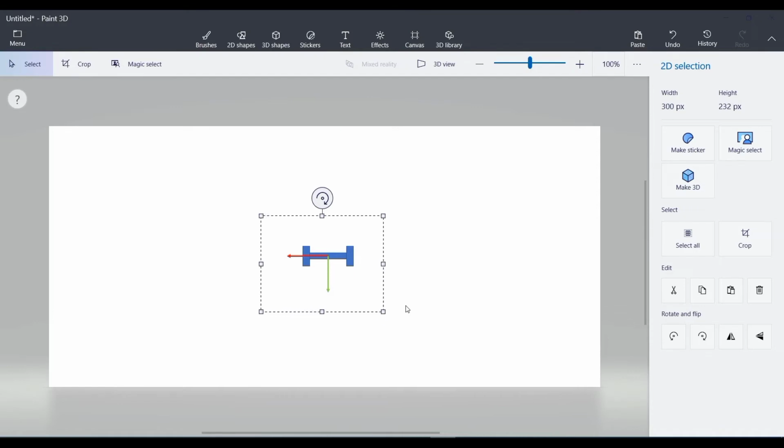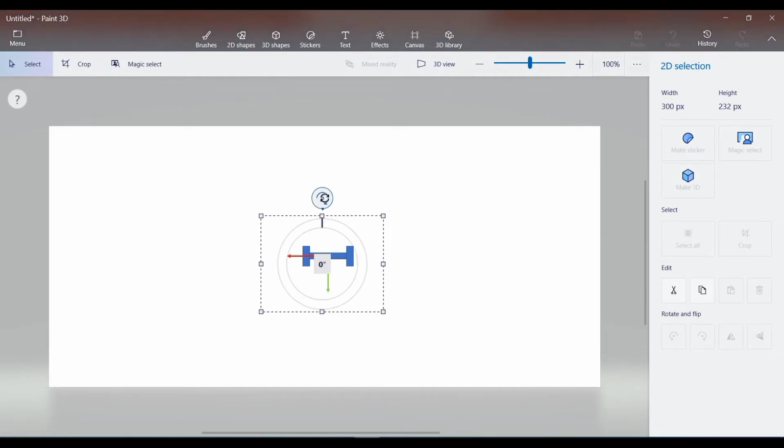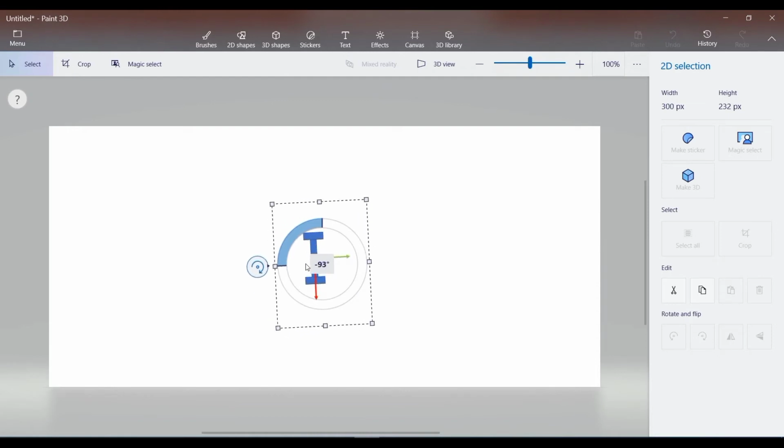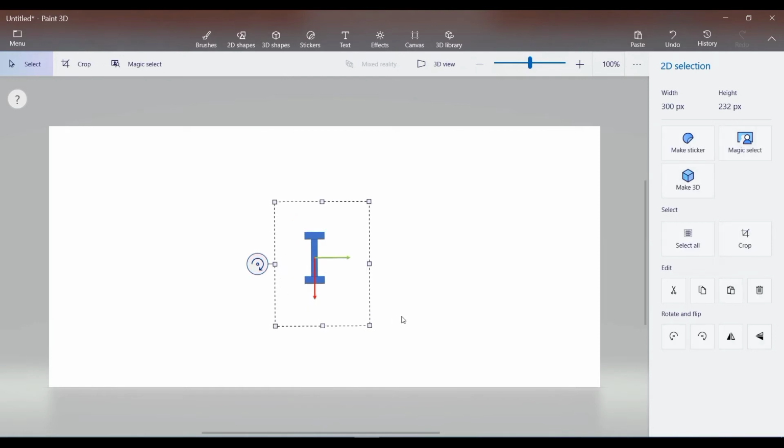As you know by now, the red axis represents the local y-axis and the green axis represents the local z-axis. Now, if we can rotate the local y and local z-axis from its default position in the anticlockwise direction by 90 degrees, we get the required configuration. So we rotate that in the anticlockwise direction by 90 degrees. And this is the default configuration that we would require for the section of one of the column members.